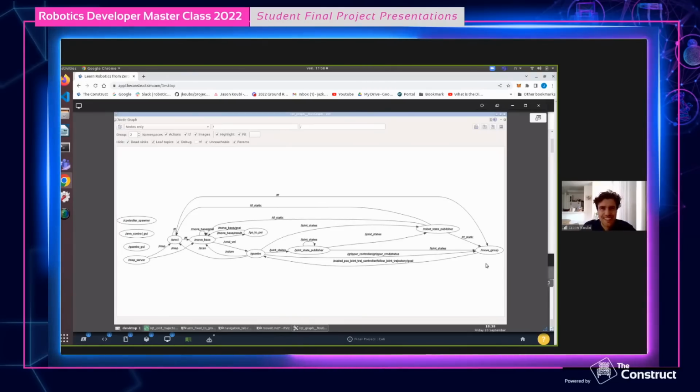So I had a few issues with my robot. Like I said, it was in turning. There is a lot of friction. I was having a hard time turning because, like I said, of the wheels, and they're not made for indoor. So I increased my velocities in the planner, angular velocity especially.